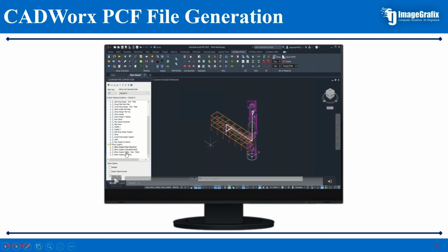Which is the PCF file generation. As such in CADWorx, prior to 2018, there was an option called the .c2 file, but there was some data loss such that the supports were not transferred properly. Those things were happening. So to overcome those problems, in the latest version we have something called C2 PCF, which